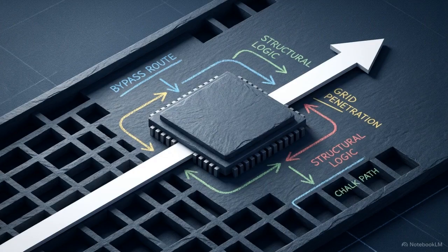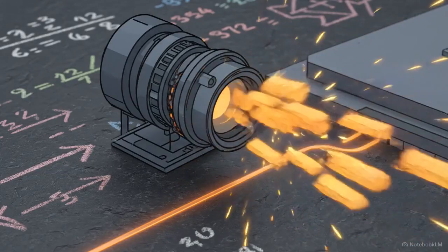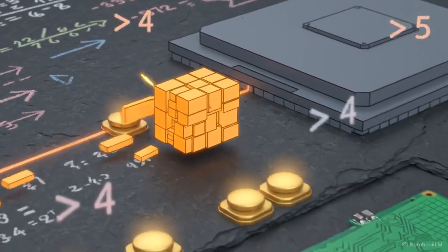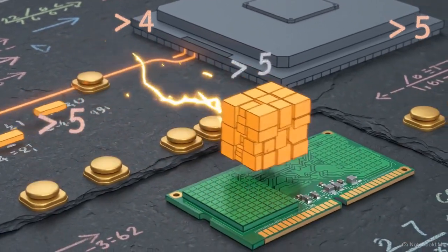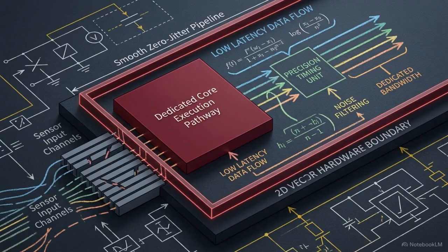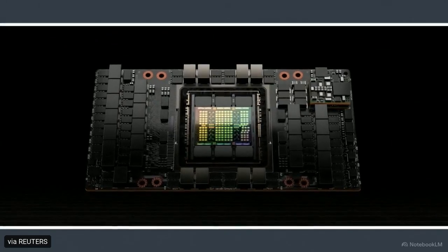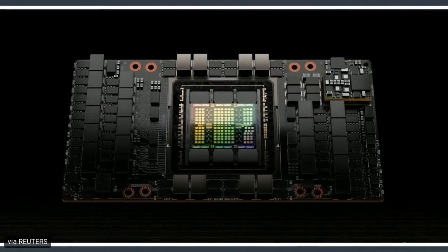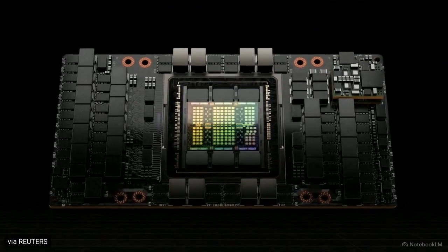This pipeline operates via asynchronous direct memory access. The external controllers are given hardwired permission to write straight to physical RAM, allowing the CPU to continue calculations without wasting a clock cycle. By physically isolating the core execution thread from the chaotic influx of environmental data, the system achieves zero-jitter deterministic latency. Inside that isolated execution core, all background hardware interrupts are forcefully masked. The chip's only function is executing math within this grid of dense circuitry.